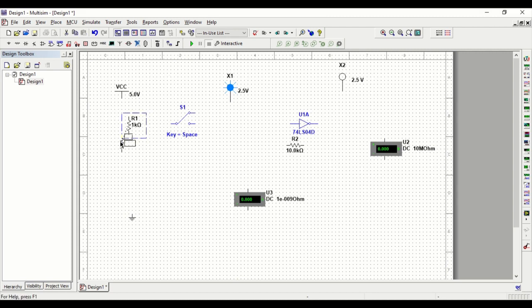You can replicate what I'm doing or simply design something different, but the idea is to give you a notion of how these digital logic gates work, and particularly the NOT gate, the very basic NOT gate. Notice that I'm actually rotating around some of the parts. I need this part to have two different inputs, high and low, that travel through the same port or channel. So I rotated that part, and I'm now moving it down. To rotate a part, just click on it and right click, and then you're going to have rotate by 90 degrees or more. And that's how parts are rotated.